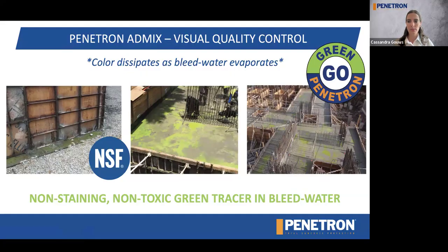Now, we're the only admixture in the world that contains a tracing agent. So when they place the concrete, the bleed water that comes to the surface is luminous green, like you can see on the screen there. Now, although it is quite a bright color, do not be alarmed. It will not stain your concrete and it is non-toxic. It is NSF 61 approved.